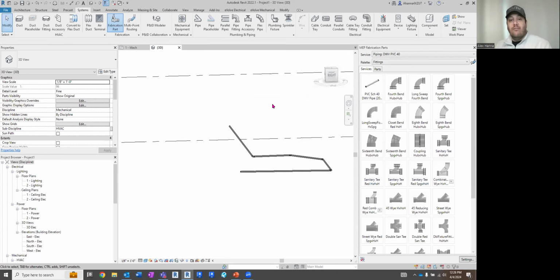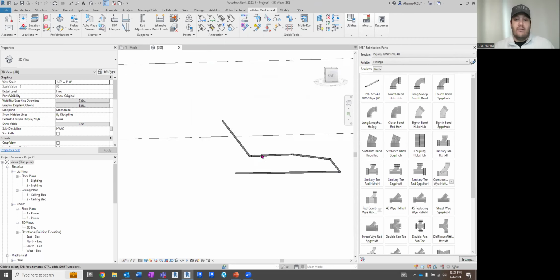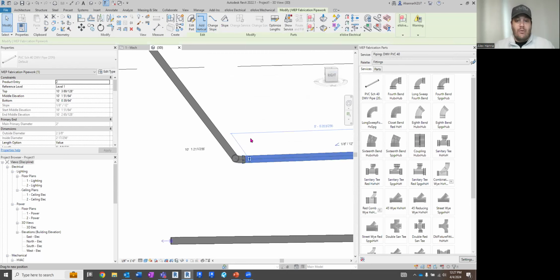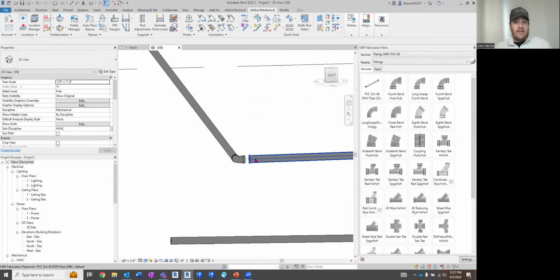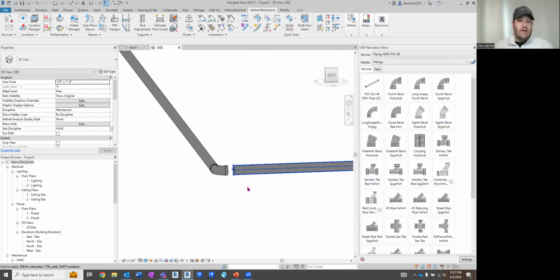When it comes to Evolve and using the Evolve tools, there's a lot of Evolve tools up here that are easy to use, like disconnect and reconnect. It happens a lot with models where if I pull this out or it slightly breaks, it's disconnected. So now when I use my tab key, it's not selecting the whole part. What these buttons will do is automatically connect them based on a tolerance. So if I'm an inch off or 6 inches off, my tolerance is 6 inches, it will bring it back together.